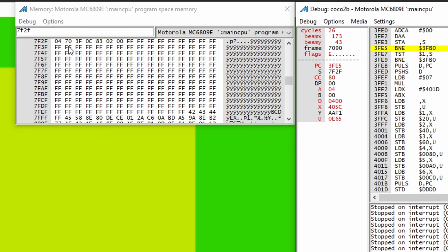I get 470. So it's like, even though I'm looking at hex, I'm seeing decimal digits. And that's because each nibble, each hex digit, is only allowed to range from 0 to 9. And once it gets up to 9, it wraps around to 0, and then the next most significant digit has its turn to increment up. So I just think it's kind of funny. It caught me by surprise a bit the first time I saw this, but in retrospect it's fairly straightforward why it would do it.